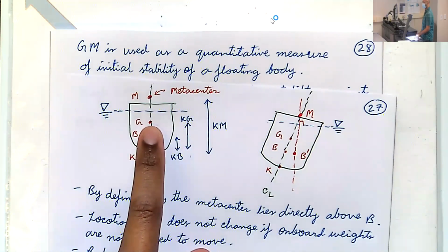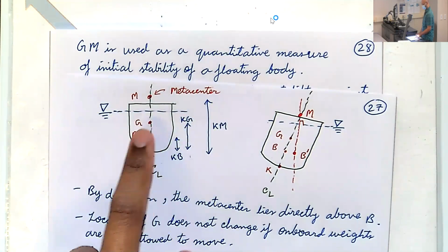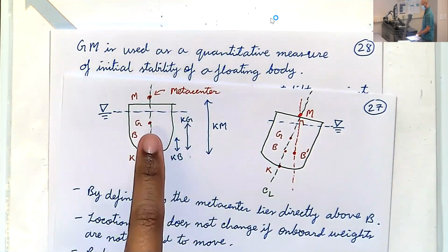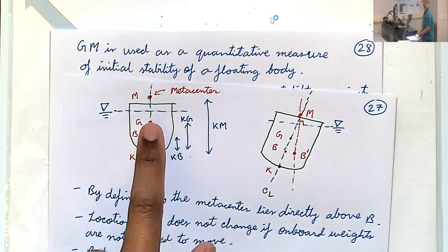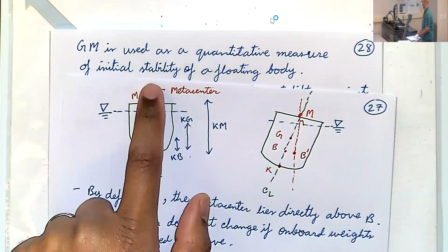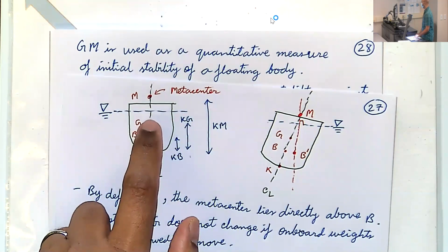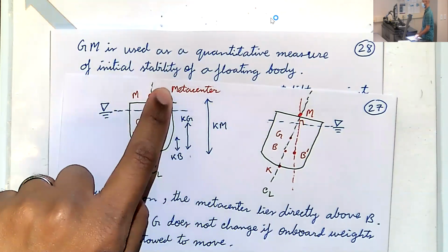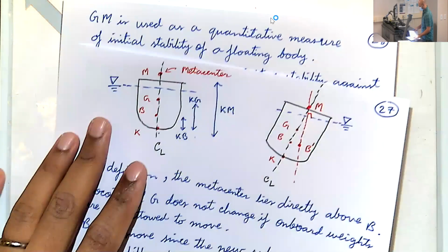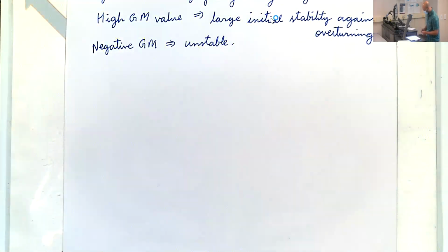You have nothing to do with buoyancy because you are sitting in the dry part. So whether you're standing or sitting has no influence on the submerged volume. The weight has not changed, just the distribution of weight has changed. You've basically taken your torso from down here to up there. So the combined CG is somewhere over there now. And as soon as this G passes the metacenter, you will flip over. So we will do all of that, at least mathematically.